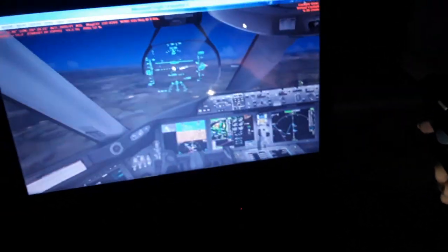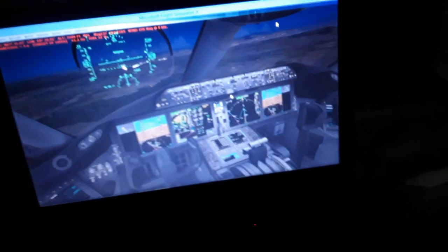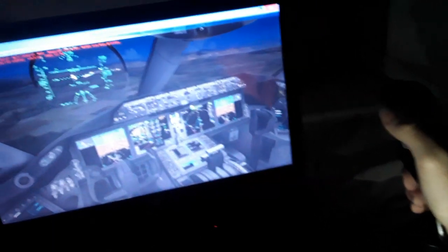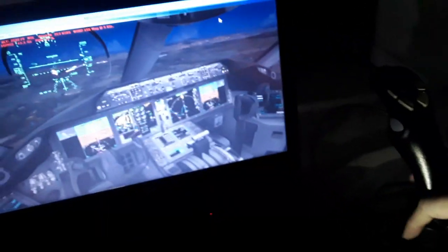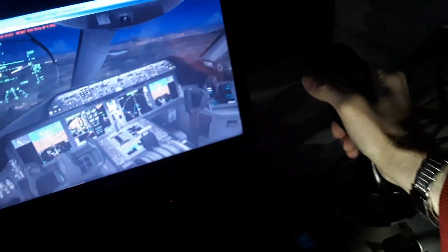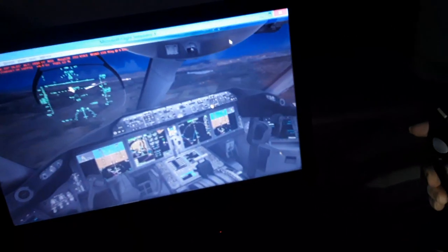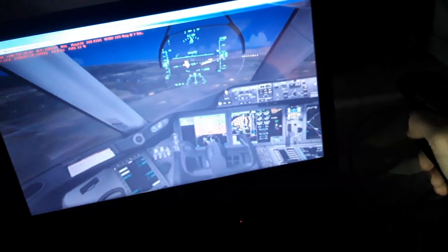Thrust manual, and we have a few more seconds for approach over here and landing. As you can see, 1 more minute. So we have some side wind, some wind gust. We need to combat the wind gust and the side wind as we are approaching for landing. So wind gust and side wind makes more difficult. You lose the heading as you approach. We need to maintain the center line over here for approach and landing.